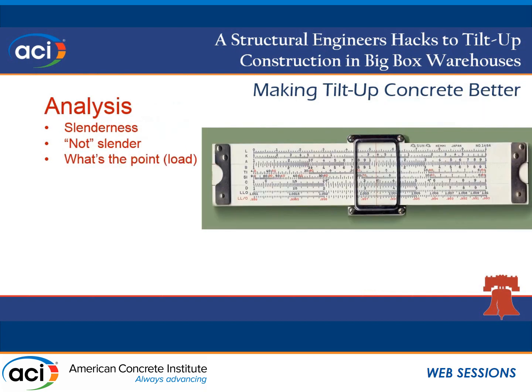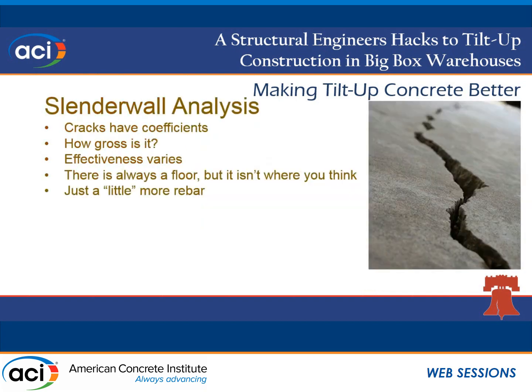Some quick tips on analysis. Slender wall analysis. This is the preferred, and I'll say correct method of designing tilt-up, but it's not the only way, okay? In the wall section, you can look at a panel as a slender element, as a not slender element, but still a wall, or as a column element. Those are all available to you. It's a piece of concrete. The concrete doesn't know that it's tilt-up.